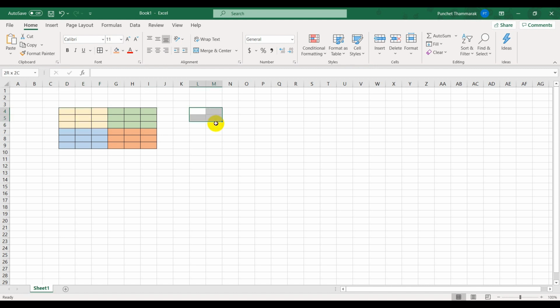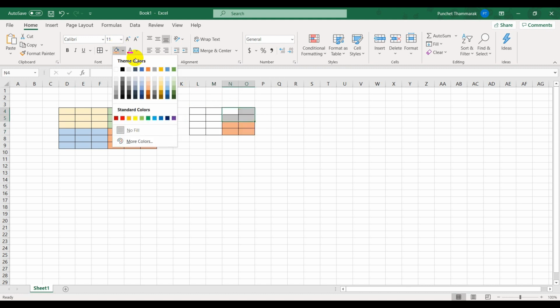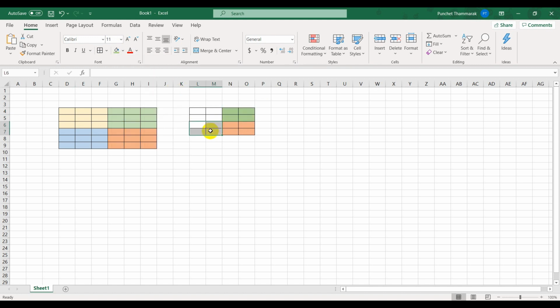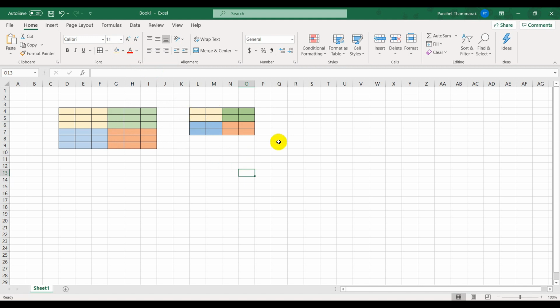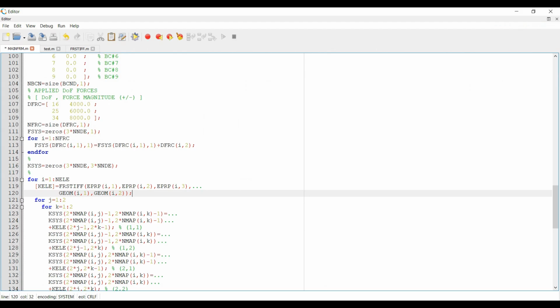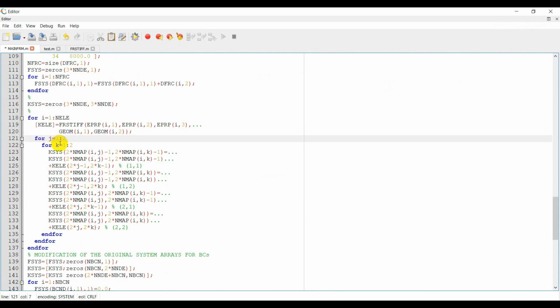So previously for the truss it was like this. So it's changed from truss problem to planar frame problem. You have 3 DOF. That means for each node you have the 3 by 3. Okay, sets like this. So our job is nothing to do, well, the J 1 to 2, K 1 to 2, that does not change, but here will be the major change.